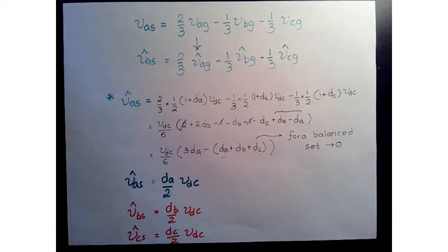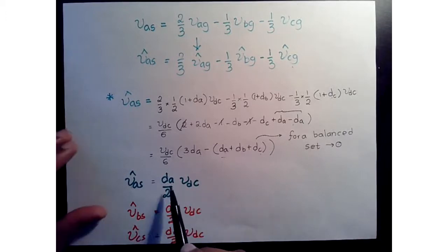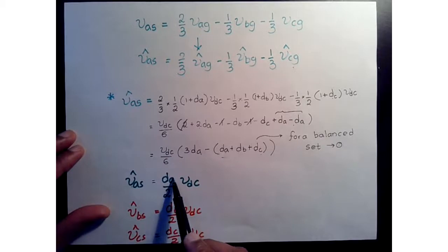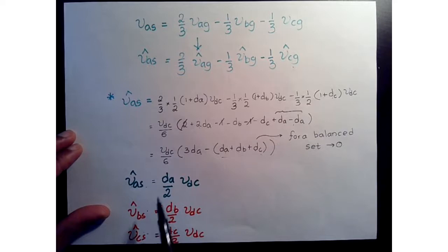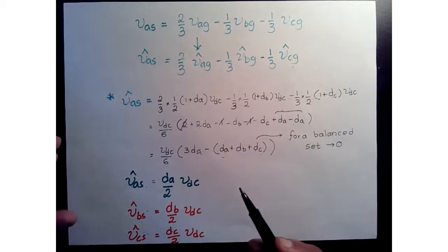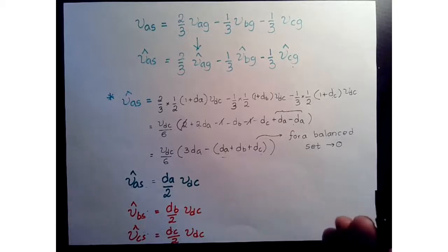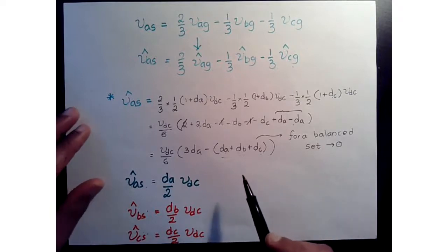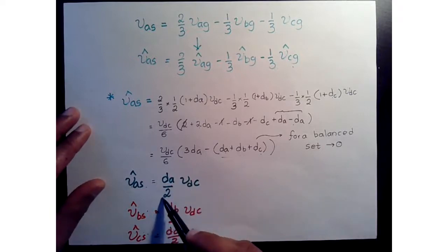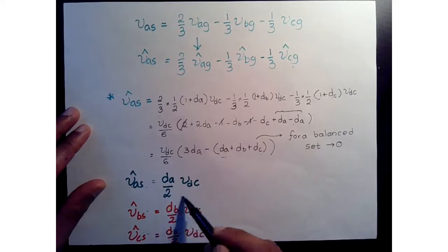Okay, so in this scenario, if we apply balanced sinusoids DA, DB, DC, then that will directly reflect on VA, VB, and VC. Okay, and depending on what our DA, DB, DC is, let's say we apply a cosine waveform, right? A cosine with the amplitude being 1, you can only reach a maximum of half DC, VDC by 2.